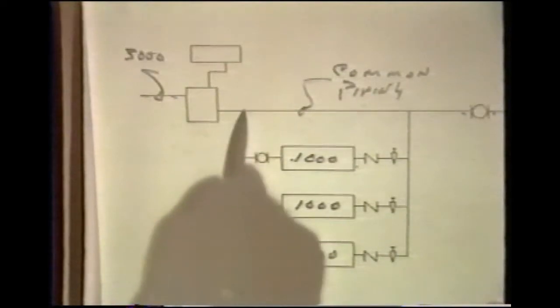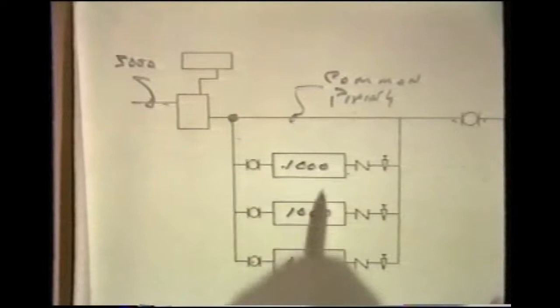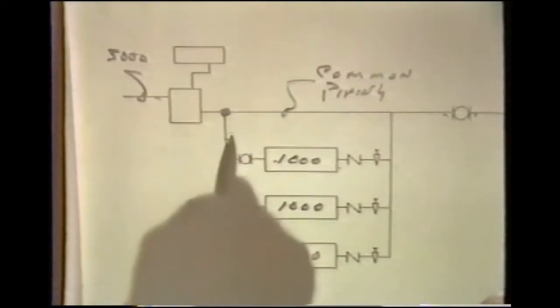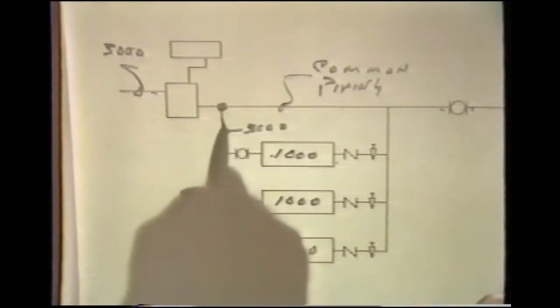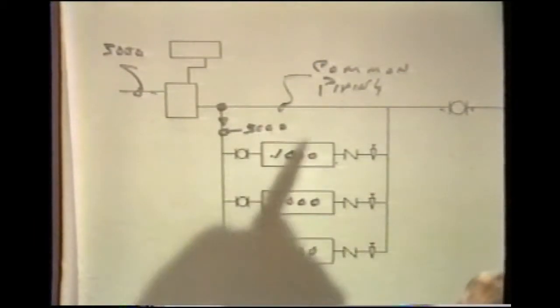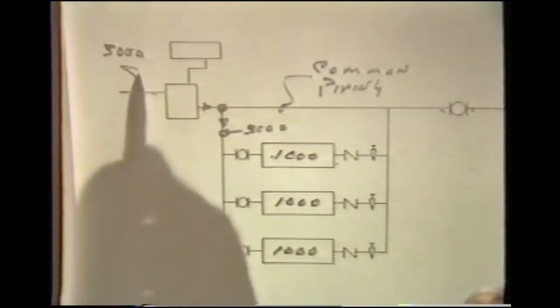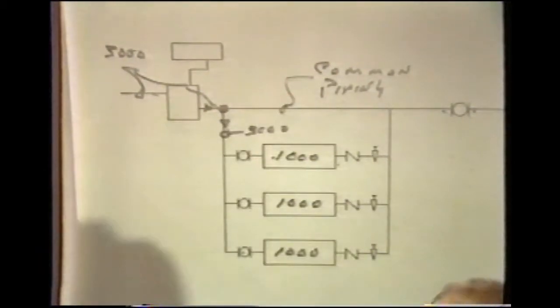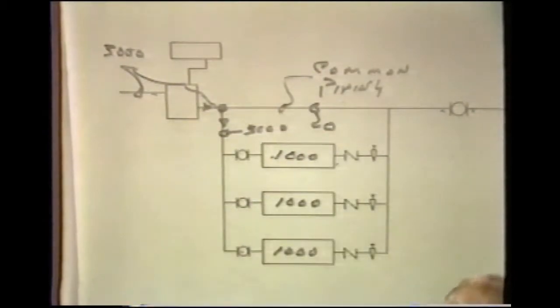Let's consider the initial full load condition, in which, in summation flow with all of the chillers in operation, we have 3,000 GPM pumping away from the T. We are introducing, however, 3,000 GPM into that T, so inasmuch as water flow into the T must equal water flow from the T, we would have zero flow in the common piping.